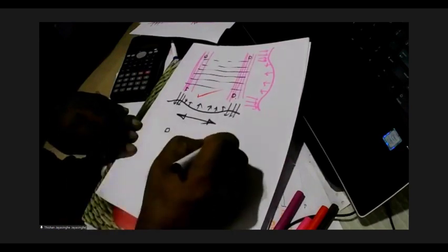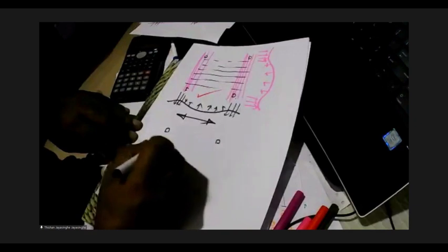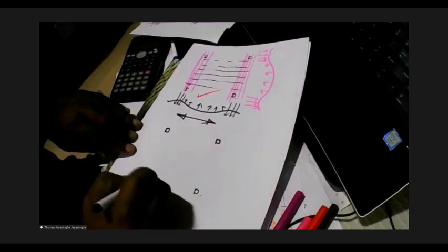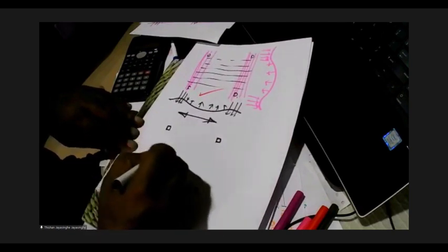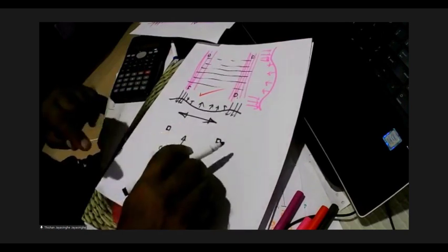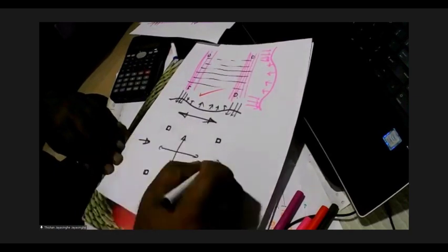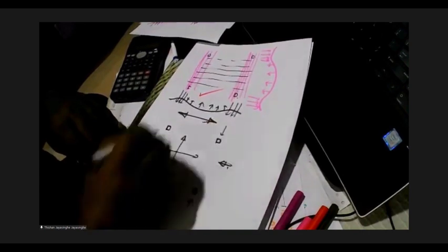So we put these in, and for the live loads, we apply the loads and find the stresses. With plate elements or shell elements, we can model it with these concentrated supports. And we can find the moments in this direction, or in this direction, due to live loads. And we know that there's pre-stress in this direction, and also some pre-stress in this direction.